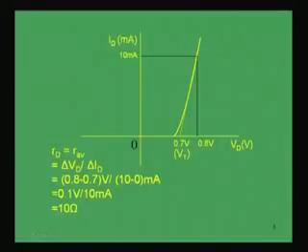So, as this region is linear, that we are approximating by piecewise linear approximation, we can find from these 2 points the average resistance that can be found out if we divide the change of voltage by the change of current between these 2 points. So, one point is this one, another point is this one.